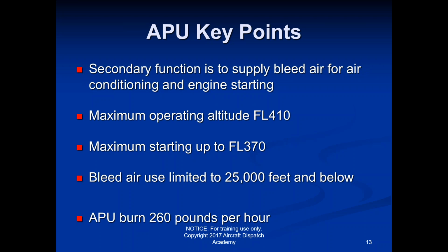But then also, when we were talking about the anti-ice systems, we were talking about how a jet engine sucks in all this air, and then it spits a lot of it out the back, but the plane itself will also take a lot of that air coming into the engines and redirect it. Instead of having it just go out the back, they'll use it for other things like bleed air for anti-ice. They'll use it for, in this case, engine starting.